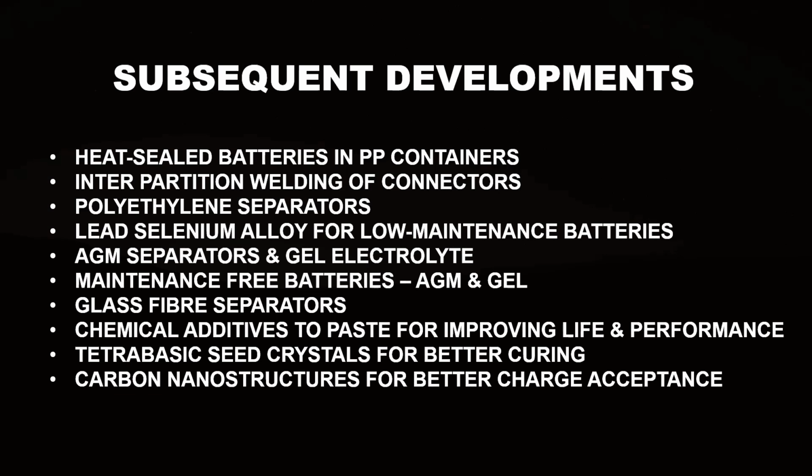Once this was done, the connectors which were used in the earlier cases that had above the cover arrangement were discarded. Here the connectors were routed through the partition of the battery container, and therefore inter-partition welding was performed. This is a spot welding operation, and this also reduced the size and weight of the lead component used to make the connectors. Naturally, with less lead being used, the cost of connectors also reduced.